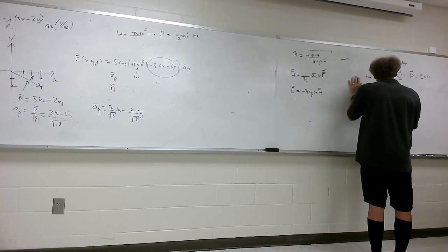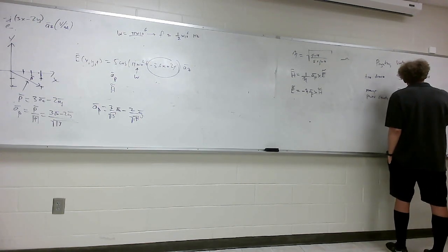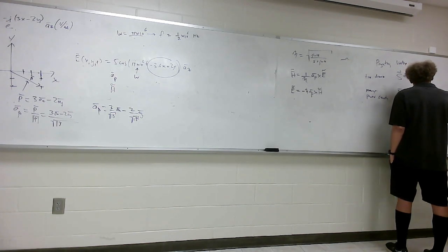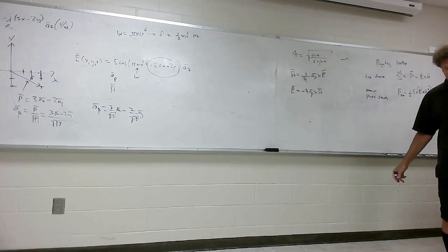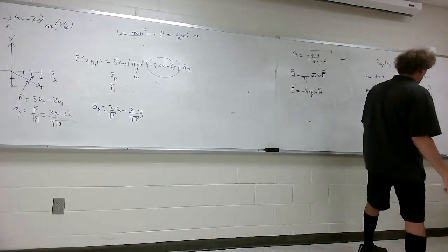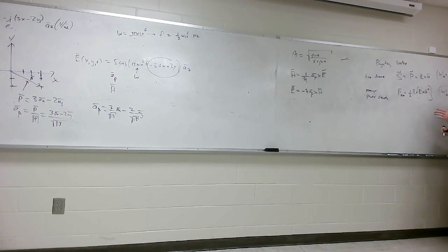power density, which is the Poynting vector, is this. And this he has in his book. P av right here is 1/2 the real part of E crossed into H conjugated. This is shown in the equation I referenced earlier. Now the nice thing about this is the units for this, both of them are going to be watts per meter squared. So it tells you the actual power density and it gives you the direction of propagation.